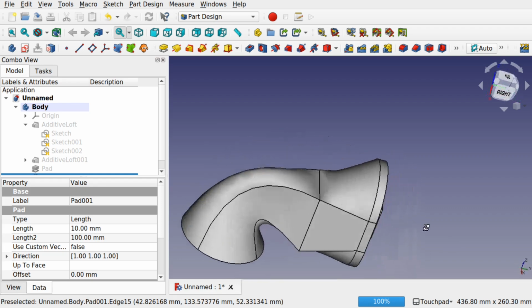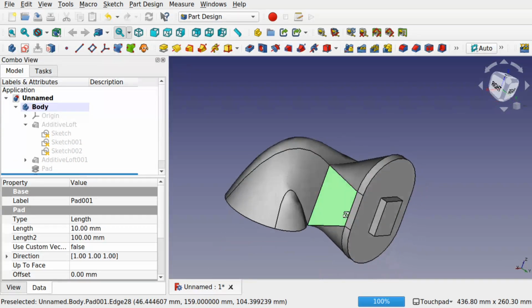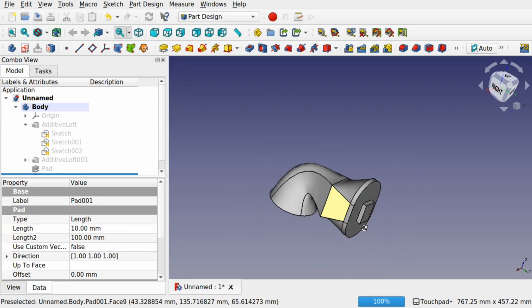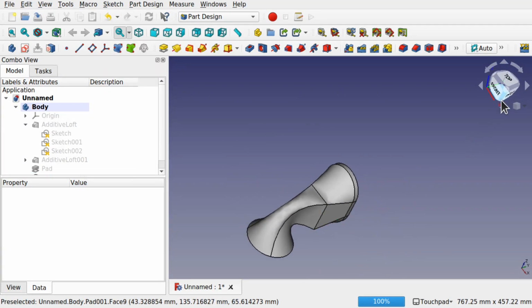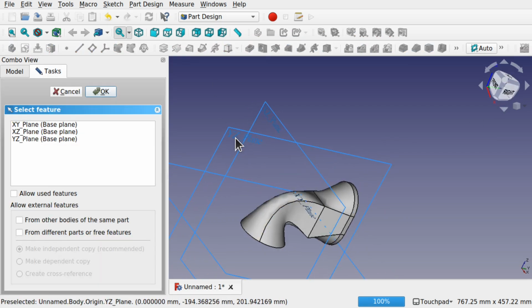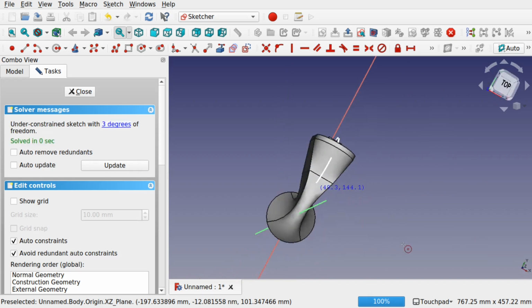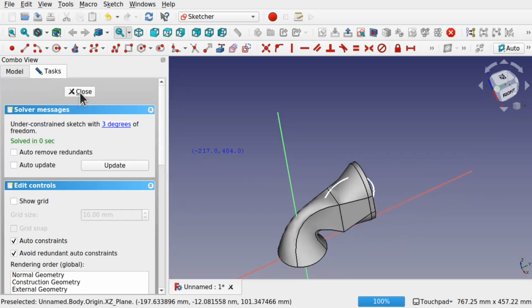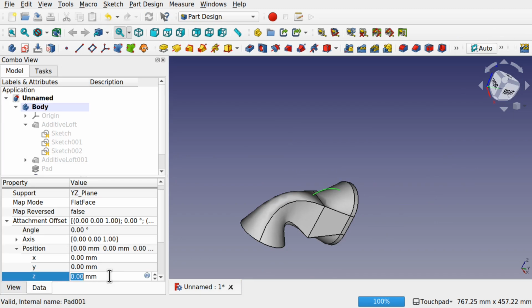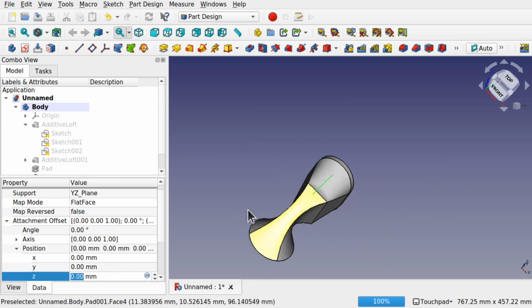Remember that also we've got these faces on the side here, which again, if I came this way, and we'll create a sketch along the YZ plane. Okay, that. And let's add a circle. I know it's not going to be the right amount of faces. Hit close. Z-axis, because normal to sketch along the Z-axis, and move that out.